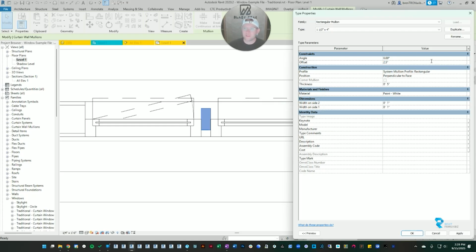And I don't know if it needs to go in the negative direction or positive direction. I'm just going to make the offset amount correct and see what happens. So I'm going to apply. Oh, and do you see it slid it the wrong direction? So it took this edge and moved it here. So that's opposite of what we need. So that means we need to do a negative offset and hit apply.